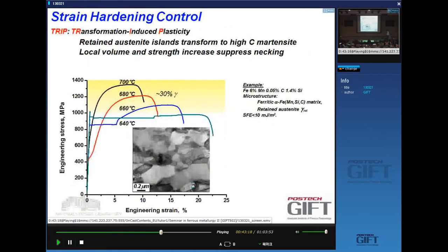Yes. Now, in terms of the manganese steels, with the TRIP effect, they tend to be interesting, yes, because they have such a low alloy content in comparison to the two other systems, yes. And because they have a low alloy content, they're easier to process, to weld, to cast, etc. So there is interest in these systems, but they're more complex because they have an ultrafine microstructure.